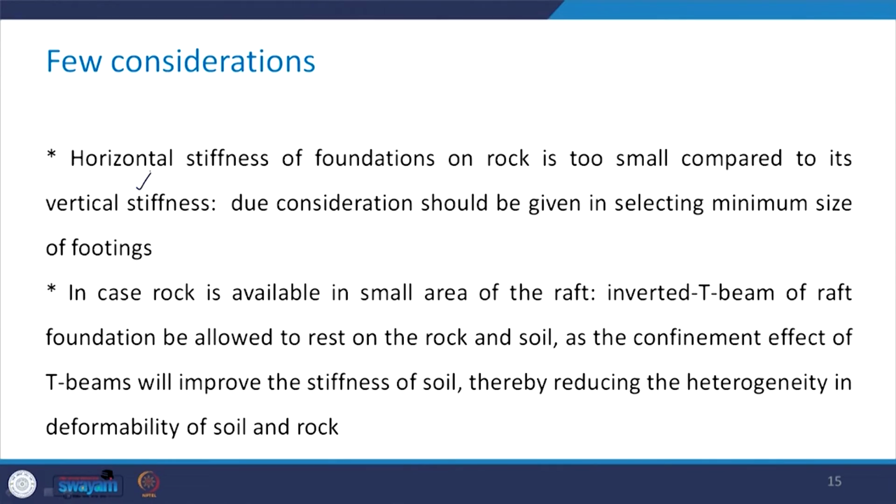Now, there are few considerations which one needs to keep in mind while going for the construction of footings on rock. We need to keep in mind that the horizontal stiffness of foundations on rock is quite small as compared to its vertical stiffness, and hence due consideration should be given in selecting the minimum size of the footings.